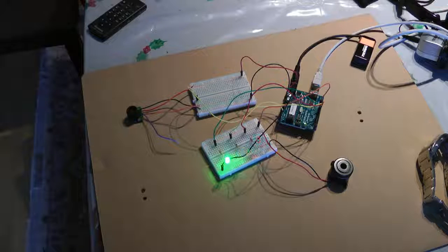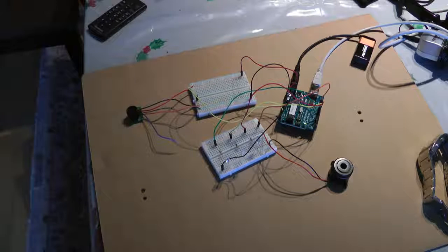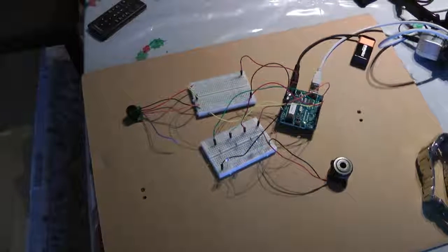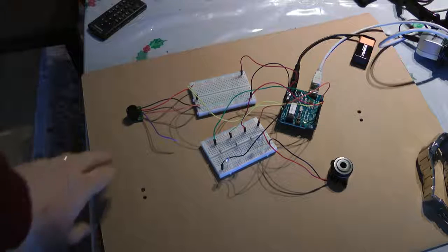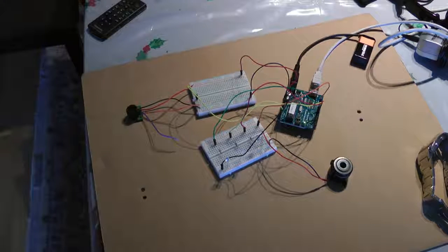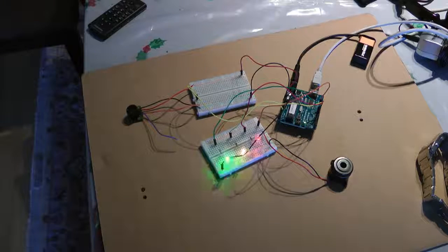You're going to run into sensors that you have to have a pin high or a pin low. And by high, I mean you have to put it in the plus 5 volts. By low, I mean you have to put it into the ground before it'll sense. Now this one, you actually put into, I believe it's low, and it'll stop sensing. But I did that, and I'm actually getting some weird readings on the Arduino. So, but anyway, now we have the sonic sensor.